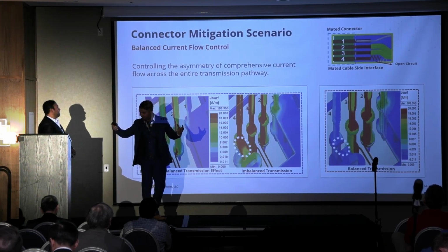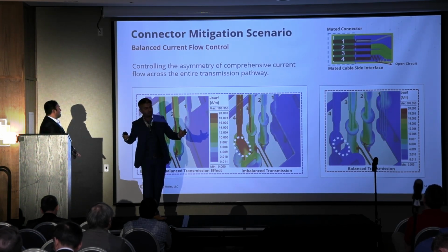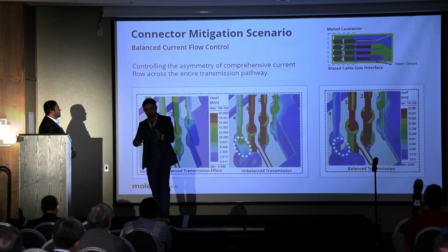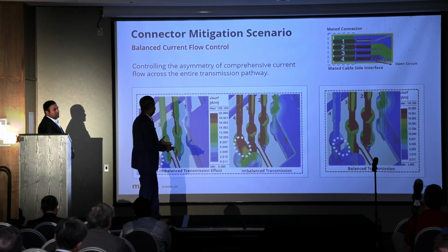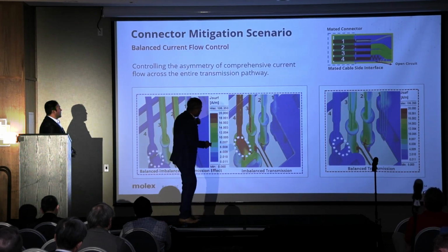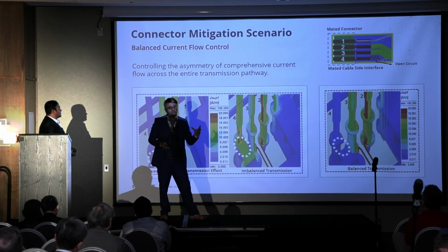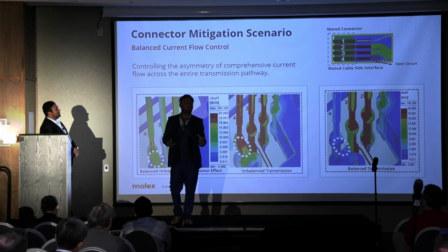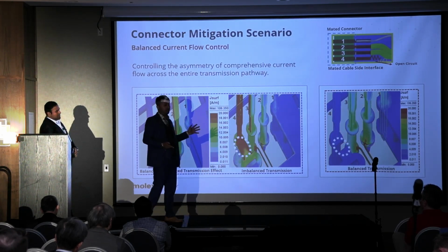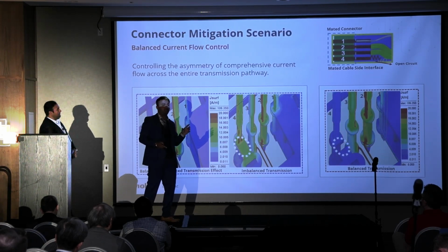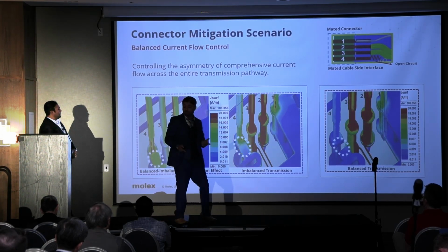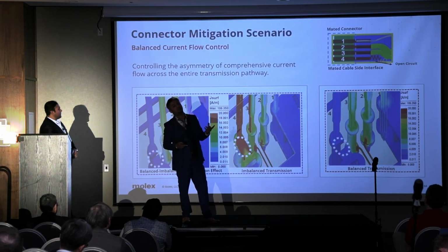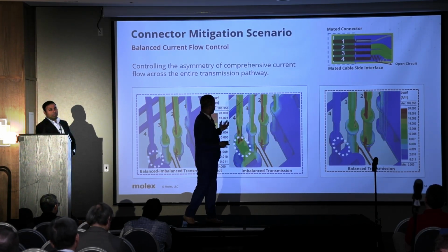So whenever a signal is propagating from a PCB from a low to a high impedance, it comes back with 180-degree phase, and it starts radiating, right? And typically when the length of these conductors is an integer multiple of a quarter wavelength, at those frequencies this behaves like a perfect antenna, like a perfect radiator. And one such frequency, what we observed, what he was talking about, is at 1.6 gigahertz. That is the quarter wavelength resonance that is happening, right?